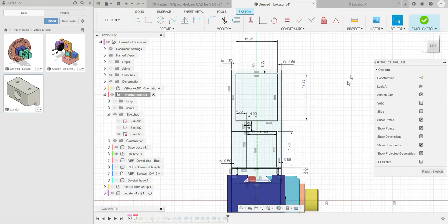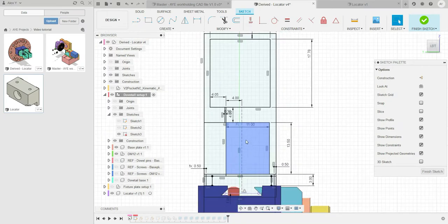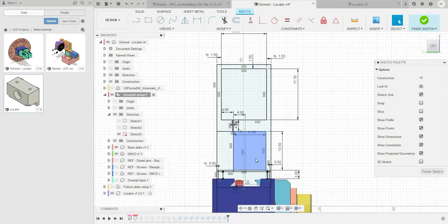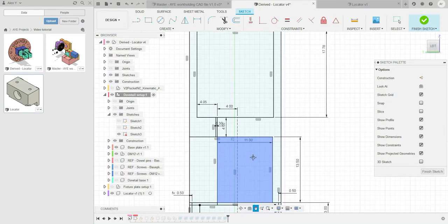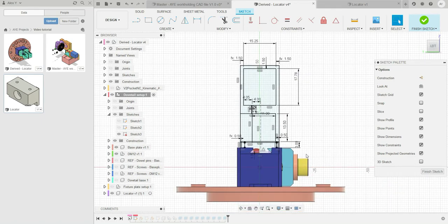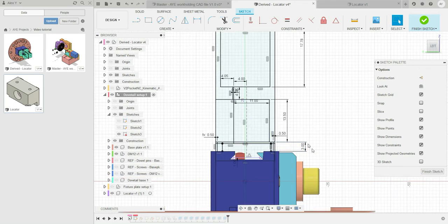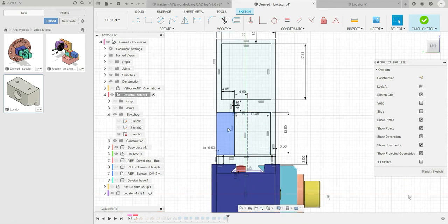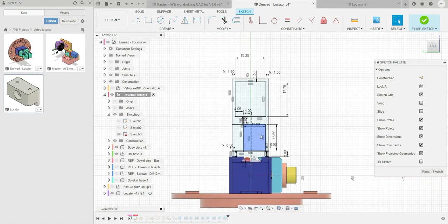So you're getting a bit of wasted stock here, but it's really not much for small parts. You're talking pennies rather than pounds, and it just makes machining so much easier, and you're comfortable that you're not going to hit anything down here, and you save so much time not having to plan for spindle clearance down here. Just buy a little bit extra stock, and this bottom lump will go to waste. It's what I do. It makes it far easier, and I recommend doing it that way.